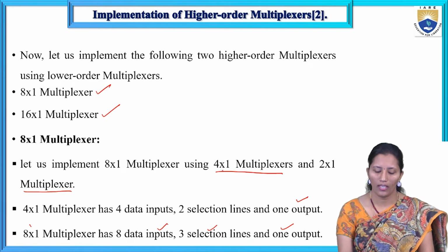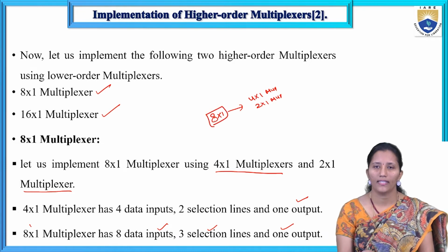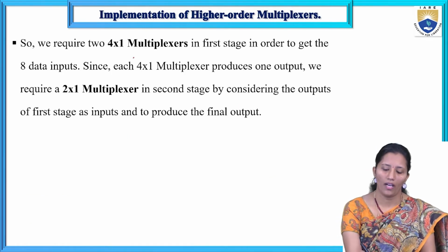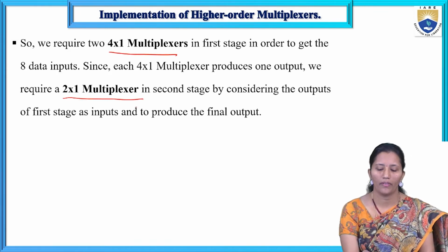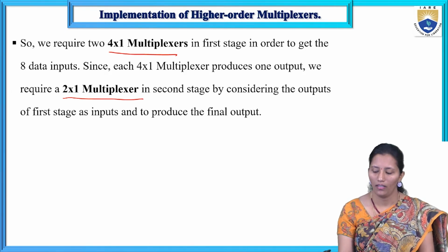To design the 8x1 multiplexer, we use two 4x1 multiplexers and one 2x1 multiplexer.